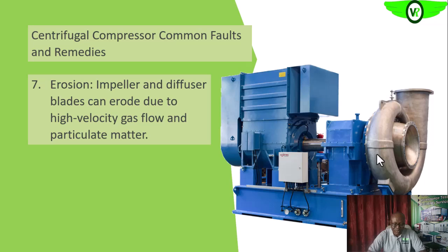So the last that we'll be looking at is the erosion of the impeller and the diffuser. As the gas is accelerated, it is of high speed. It's actually impinging on this component, and especially if the gas contains some particles, that will increase the erosion, that is the wear of the surfaces of the impeller and the diffuser. So what are the remedies to this?